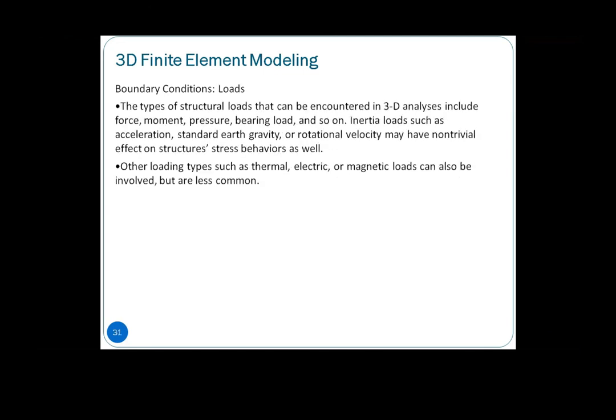The load, we have many types of loads. Under solid mechanics, we have force, moment, pressure, bearing load, and so on. We also have inertial loads like acceleration. You can even add the standard Earth gravity to consider the inertia or the weight of your bodies, and rotational velocity. So these are the available loads for us to include in our analysis of solid mechanics problems. For other types of analysis, you have other types of loads like thermal, electric, magnetic loads that can also be involved, but for other types of analysis.